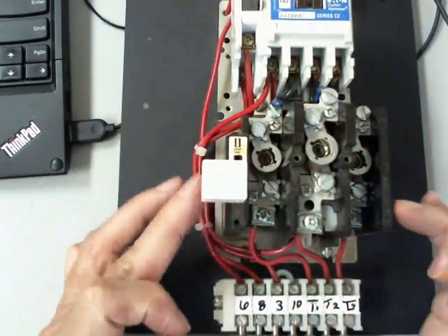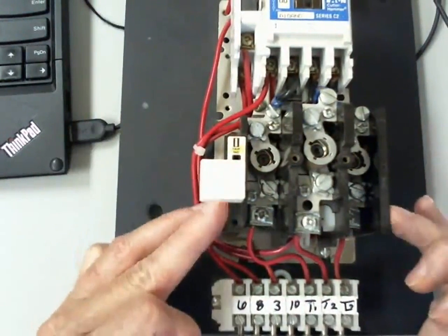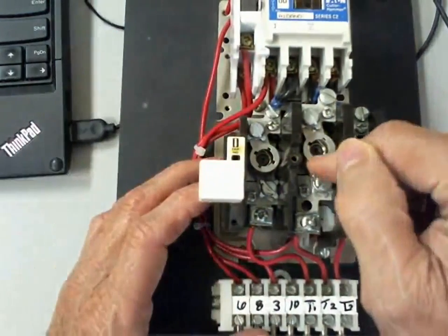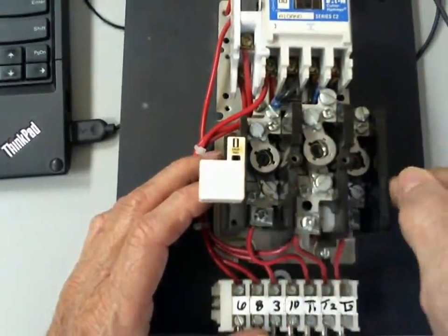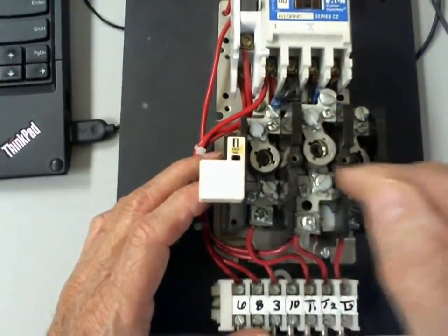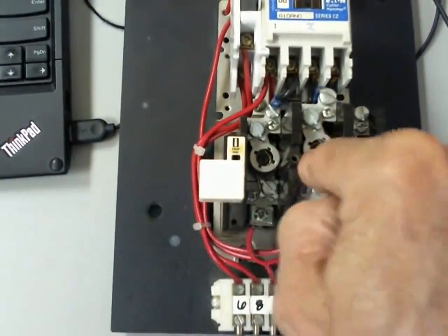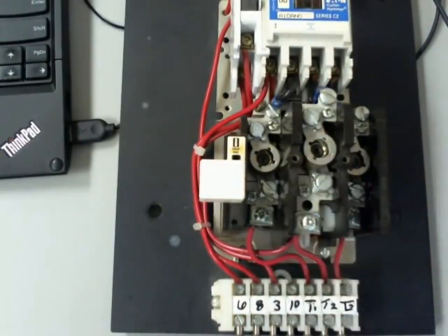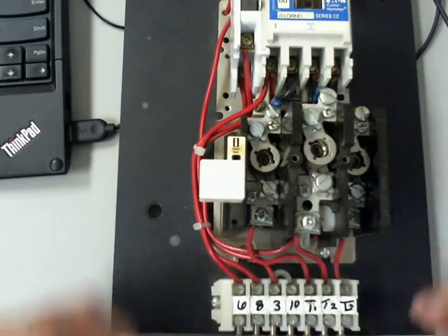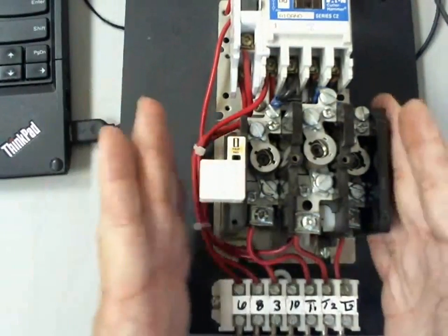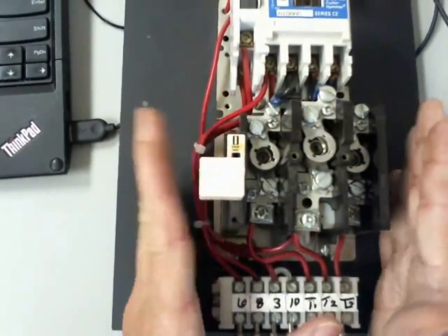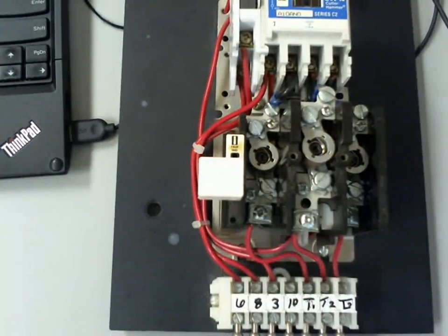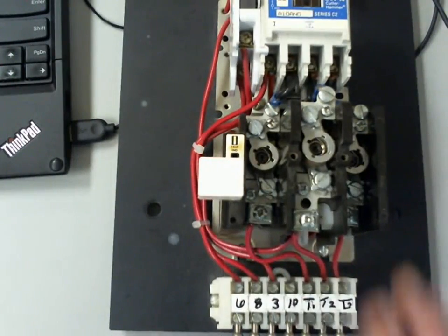Originally, they only sensed L1 and L3, because they had in their mind that if you have a fault, the current would go through L1 or L3. So originally we tripped on L1 and L3, and they didn't sense L2. Well, they found out that was wrong real fast. So you might run into an old magnetic starter out there that's got 2 reset buttons on it, and it's only going to be on L1 and L3. If you ever replace it, you need to go into these, because they found out that L2 could overload and not affect the other 2, by the way.